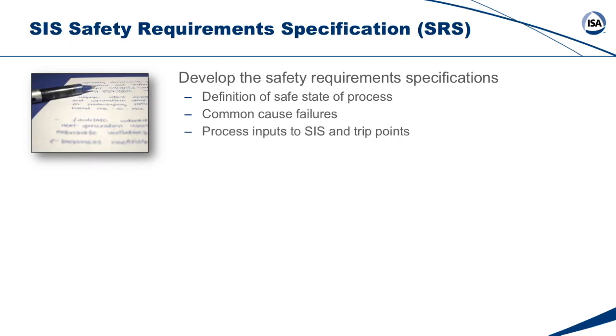What are the inputs to the safety system? The integrator doesn't know what inputs you need. They certainly don't know what trip points or shutdown values or alarm values you're going to have. And again, the specification here is the requirements. It's not the implementation. It's not buy brand X logic solver and brand Y sensors. That's not a specification. You need to tell those vendors and system integrators what their system needs to do, because you can go to every system integrator and they'll all provide you a different solution, but they all need to meet this requirement specification.